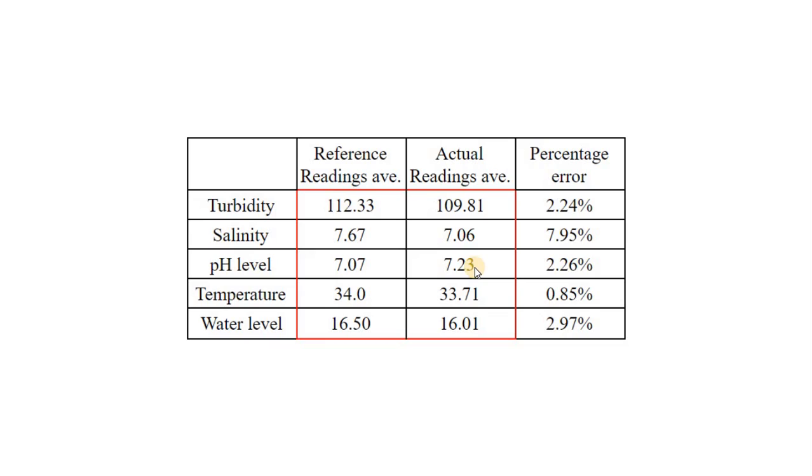The water level was measured through sonar. Since level could not be verified through laboratory testing, an analog instrument was used, a steel tape measure. Human error likely contributed to the difference between the readings taken from the sensor and readings taken from the steel tape measure because it was taken through visual observation only. The temperature parameter was also not verified through a laboratory. An alcohol thermometer was used to compare with the temperature taken by the digital sensor. Human error was also expected when taking measurements through the alcohol thermometer, as level indicators were incremented only by quarters, resulting in less accuracy.